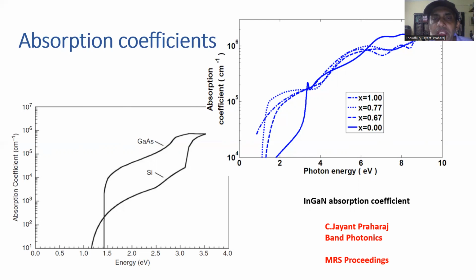That means getting good tunnel junctions in tandem cells is different, and also getting good contacts to the P layer in just the graded layer solar cell designs is also more difficult. And so those cases need careful design in order to obtain the desired level of solar cell power conversion efficiency and optimization.